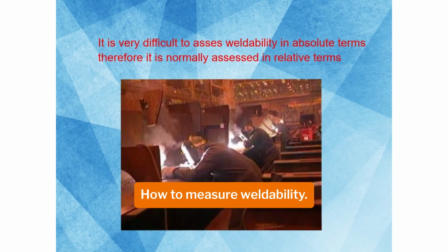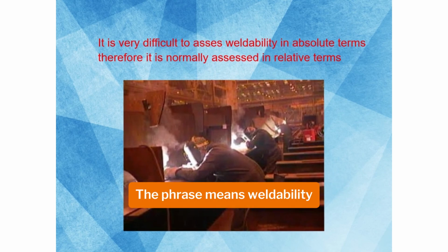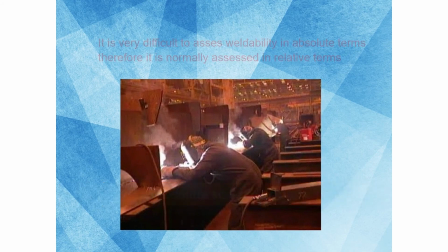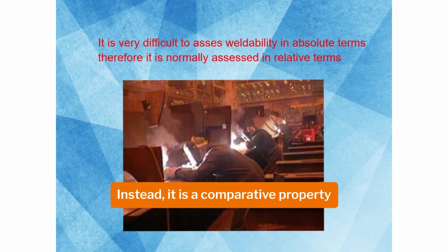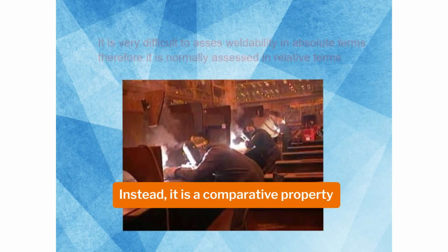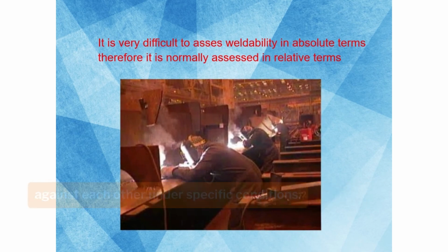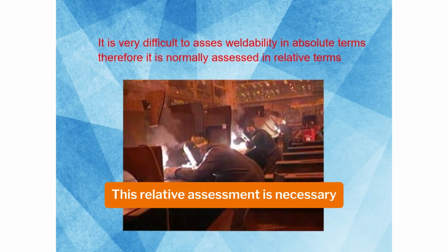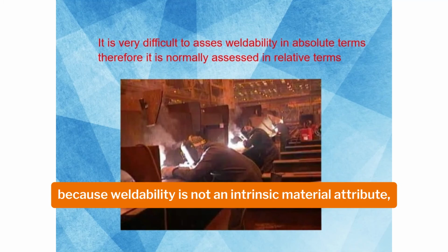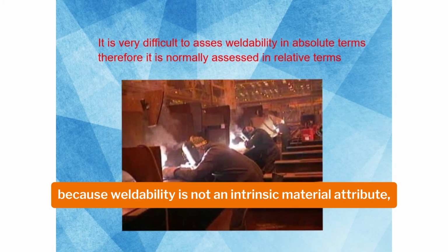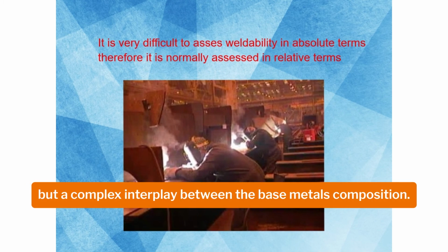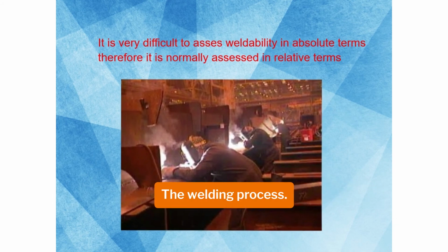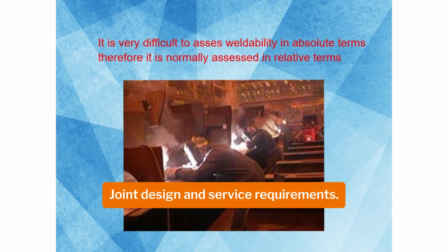How to measure weldability? The phrase means weldability cannot be defined by a single, universal measurement or an absolute scale. Instead, it is a comparative property evaluated by ranking materials against each other under specific conditions. This relative assessment is necessary because weldability is not an intrinsic material attribute, but a complex interplay between the base metal's composition, the welding process, joint design, and service requirements.